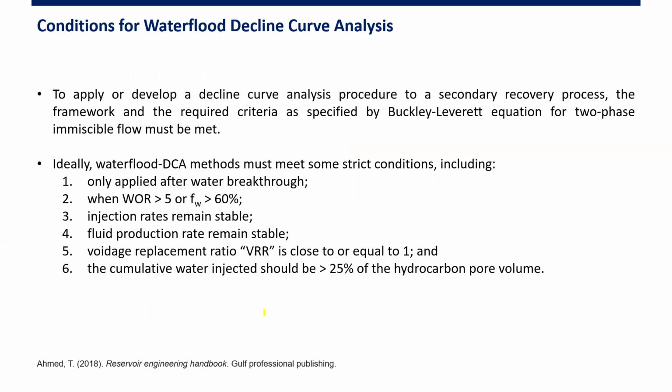And to apply or to develop a decline curve analysis procedure to a secondary recovery process, that is to say the water flood process, the framework and the required criteria as specified by Buckley-Leverett equation for two immiscible flow must be met. Okay, so if you want to perform water flood decline curve analysis, we must put into place this Buckley-Leverett equation for two-phase immiscible flow. Okay, this condition must be met.